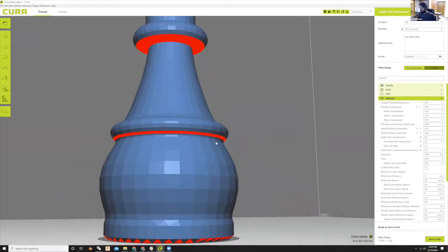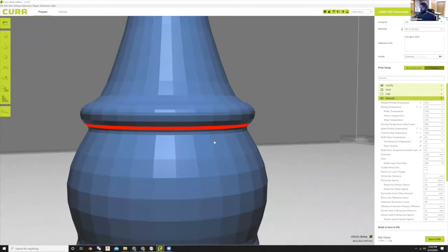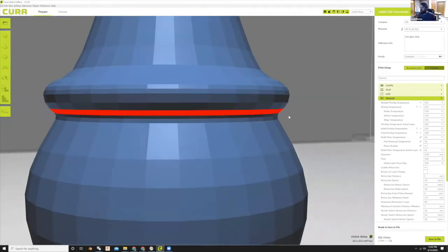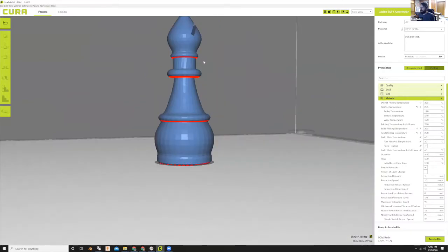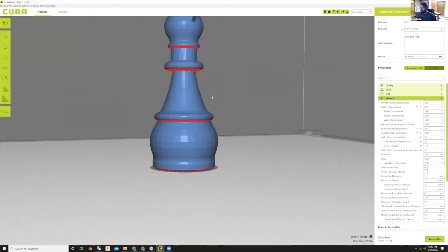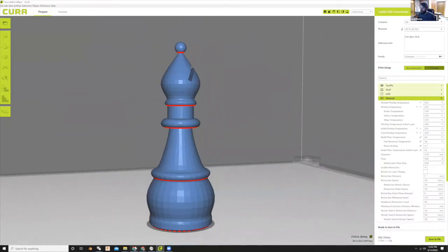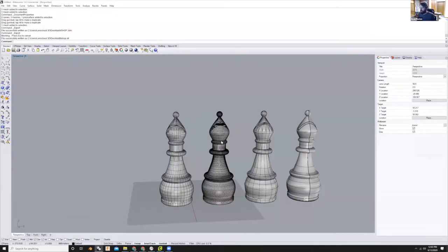Printers, you should do like, I mean, 45 degrees is safe. Anything more than 45 is going to be somewhat problematic. So it's giving these warnings here. What I could do in my model is adjust that geometry by re-sketching.